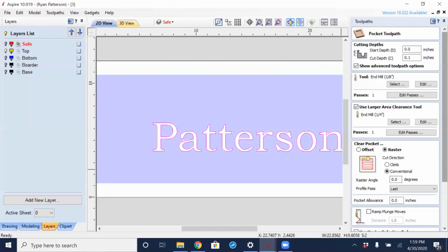So keeping things aligned after a tool change. Well, everything should just be already aligned. So there shouldn't be anything to have to keep in alignment after that. So yeah, the main thing is the Z0, zeroing it off of the same location every time, and then also not moving your product and your material on the table. So as long as your product and your material didn't move, it's not going to go anywhere.